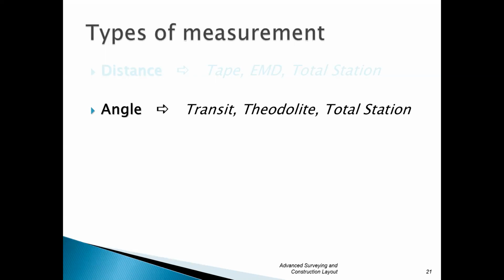The theodolite was the European counterpart to the transit. These guys were much better than these, because these had steel plates that were graduated like protractors. They were really hard to read. Theodolites used etched glass. They were more precise. They were much better.